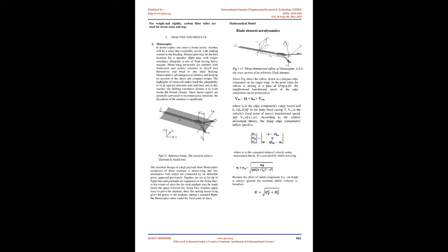Frames. Features of designed drones. Maximum vibration isolation, easier on the flight controller, smoother video, noise reduction, electronic longevity. Lightweight design, weight centralization, maximum payload, increased battery life, overall efficiency. Structural rigidity, strong airframe, but not overbuilt where unnecessary.